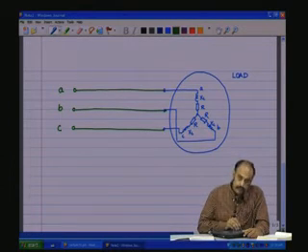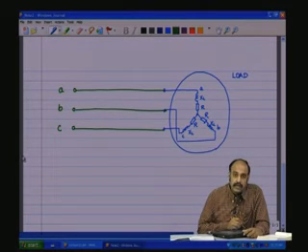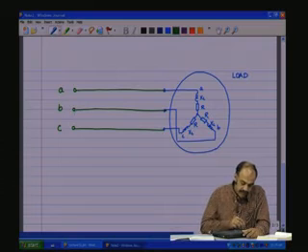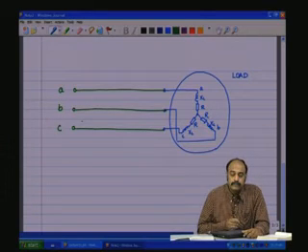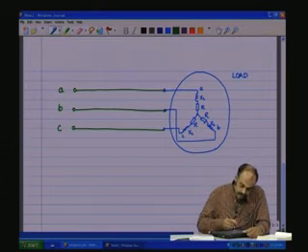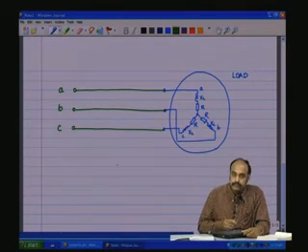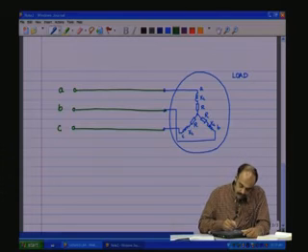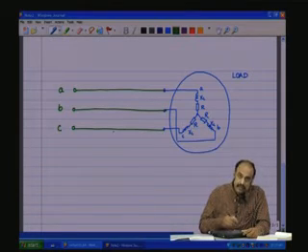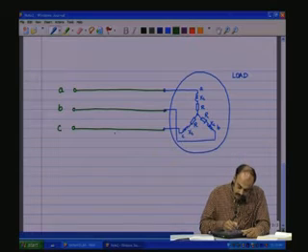So, in order to reduce the reactive currents drawn from the source side, so that the ratings of the source or the generator can be more optimally used, normally in the industry they try to improve the power factor from the line side by connecting a capacitive buffer in between, to act as a reactive generator.